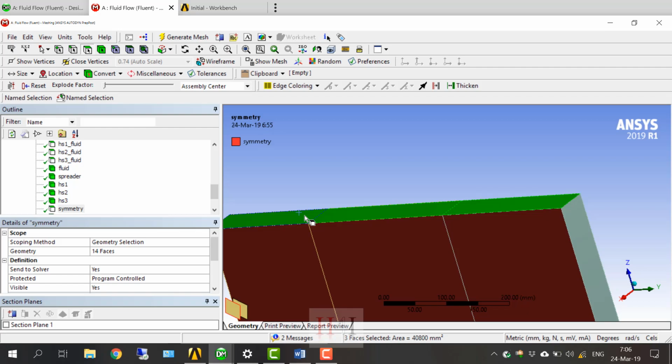And you can define this surface and this surface, both horizontal. So you can calculate a value at this height and define it as a constant, negative 10 Pascal maybe, and you can define here a constant 0 Pascal. Now you define the two variable pressures which consider the height, and here, because you can't insert an equation, you define it as a wall. And it will not affect the solution because there is no flow here at all.